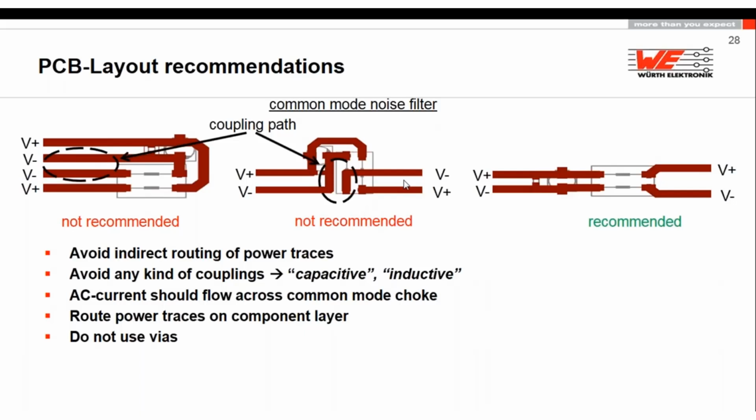This is also a dangerous zone. This can happen again. I don't know, it's the electromagnetic field, but it can contaminate again because it's too close to each other. Consider a common mode choke like a transformer, which is galvanically connected. You have the noisy area, the dirty area, and you have the clean filtered area.